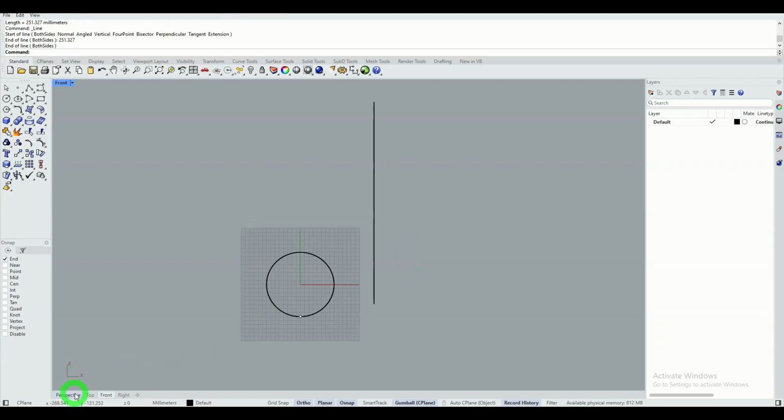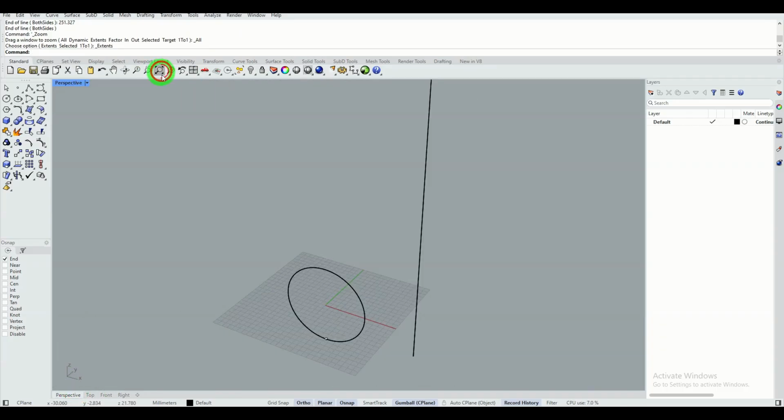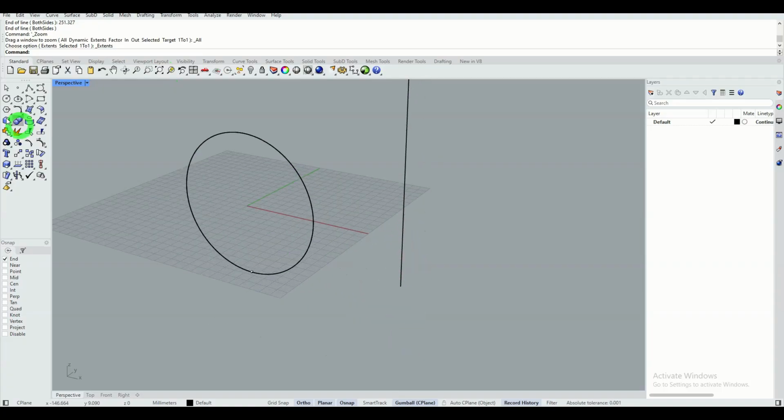Then I'll draw a rectangle for the center using the rounded option. The center of the rectangle is here at this vertex of the line. The first value is 5 millimeters, the second is 20, and the radius is 1.